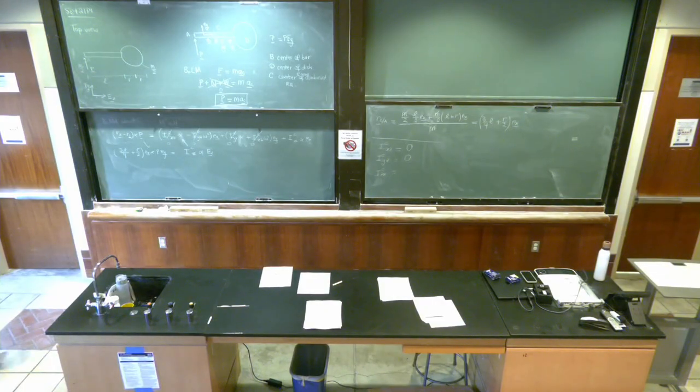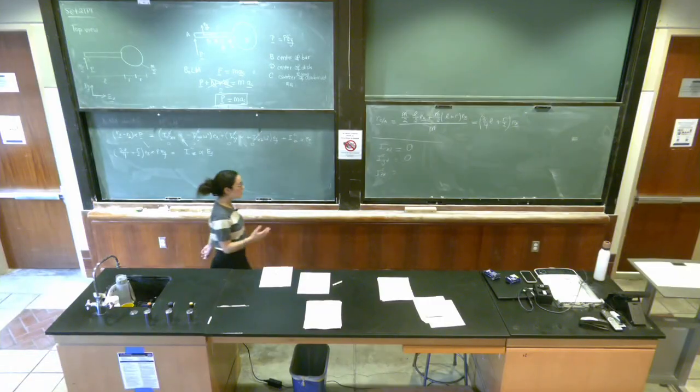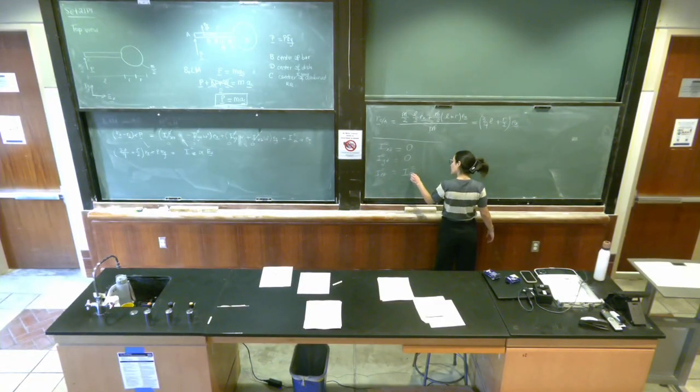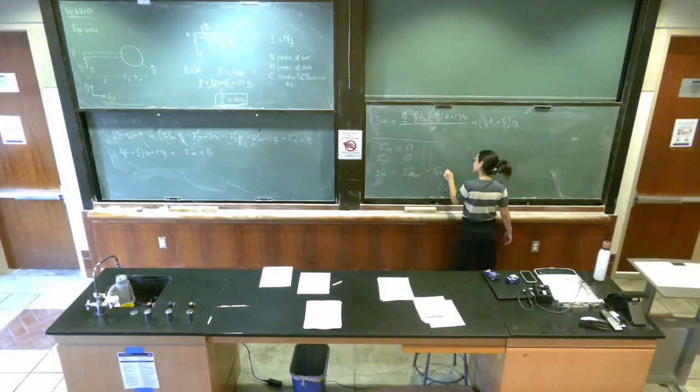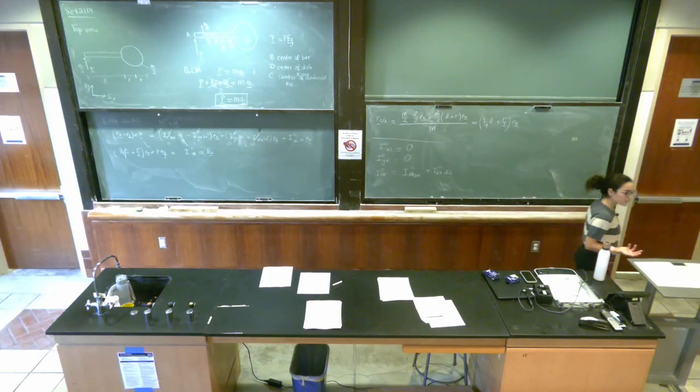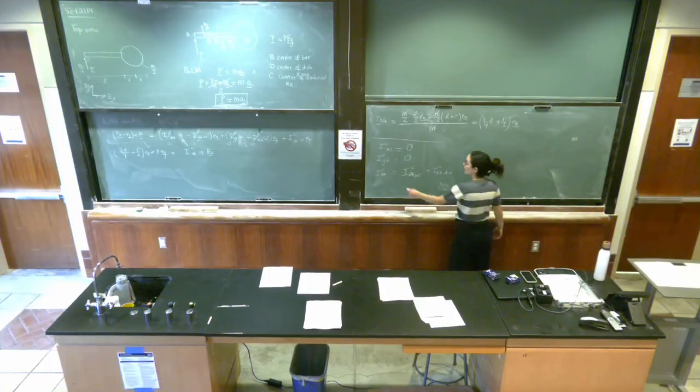Okay, so the moment of inertia of the body is ICZZ of the bar plus ICZZ of the disk. How come I can add the moments of inertia like this? Integrals, exactly. Remember the original formula to calculate ICZZ: the integral over the body of x squared plus y squared dm.